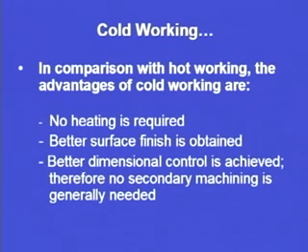Now, within deformation processes, we can either go for cold forming operations or we can go for hot forming, or in other words, we can either hot work the metals or we can cold work the metals. Now, depending upon different advantages and limitations, we have to make a decision, either we have to go for hot working or we have to go for cold working.